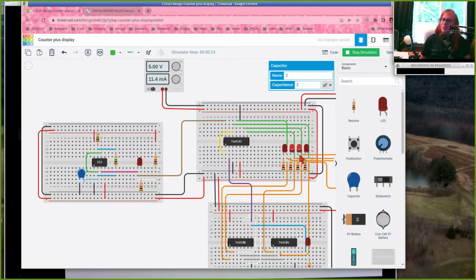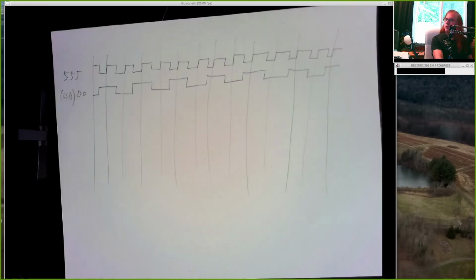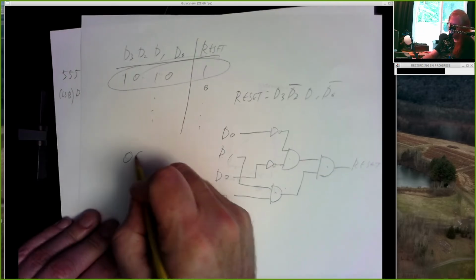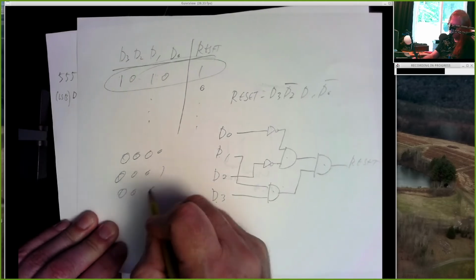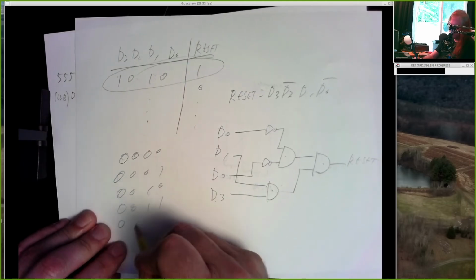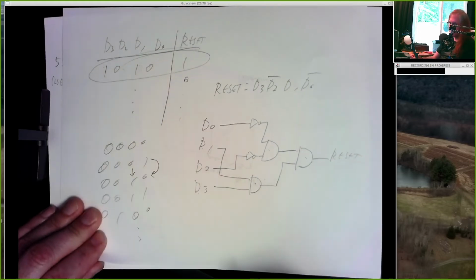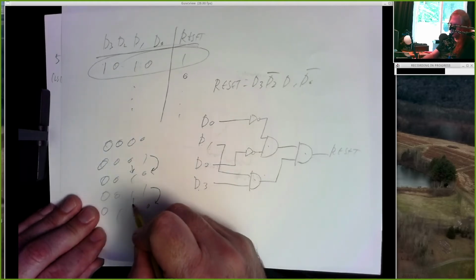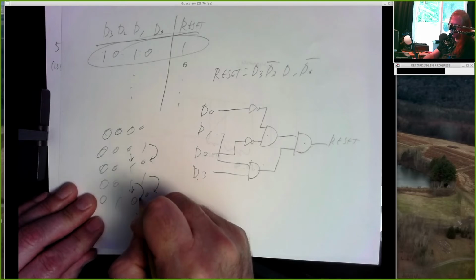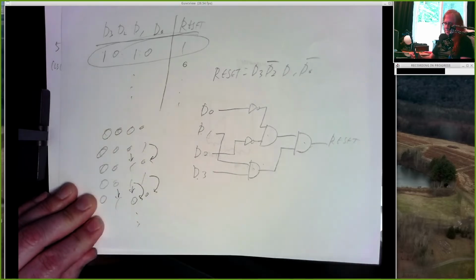And that also goes along with the data sheet describing the chip, because we take the output D0, you feed that into input B, which is a negative edge-triggered input on that next JK flip-flop. And if you write out the numbers from 0 through 9 in binary, you observe this pattern that every time this bit changes from a 1 to a 0, the next bit toggles. This bit changes from 1 to a 0, the next bit toggles. And when this bit changes from a 1 to a 0, the bit next to it toggles, and so on.